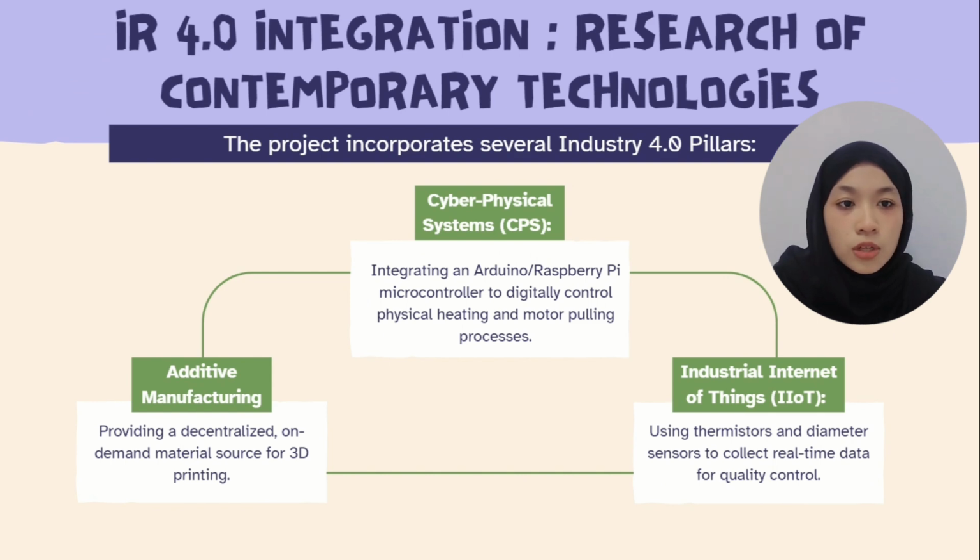For CPS, we are integrating an Arduino to digitally control the physical heating and motor cooling process. For IIoT, we are using thermometers and diameter sensors to collect real-time data for quality control. And lastly, for additive manufacturing, we provide a decentralized, on-demand material source for our 3D printing.